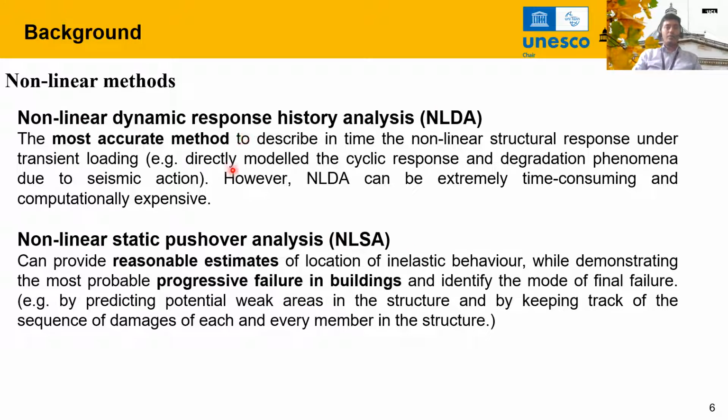The nonlinear dynamic analysis is the most accurate method available in practice. However, this method is extremely time-consuming and computationally intensive, even for a single ground motion record. So it is not very practical in, for example, a design setting, unless it is theoretical.